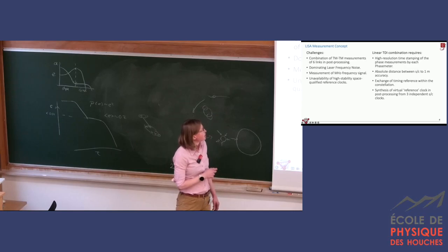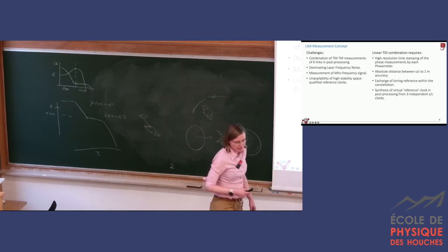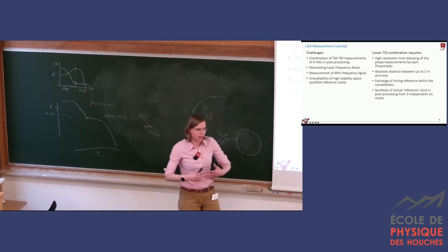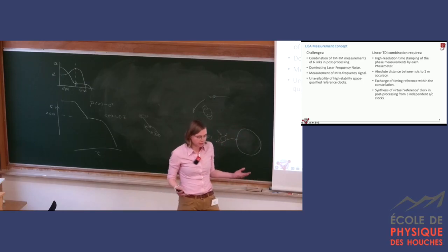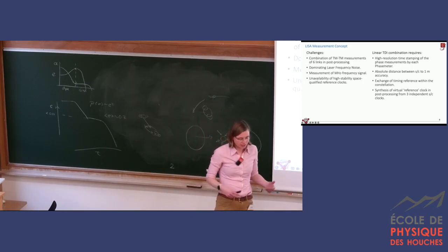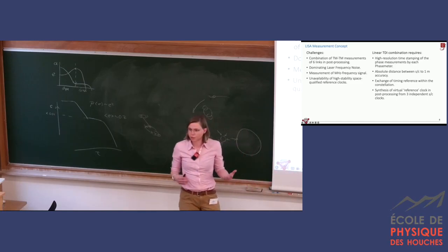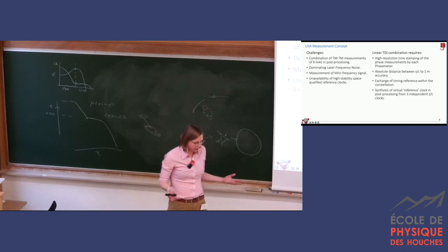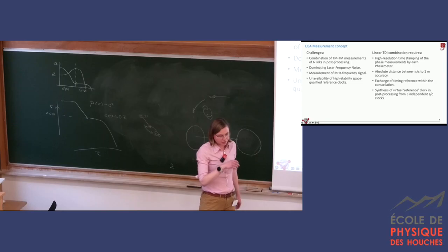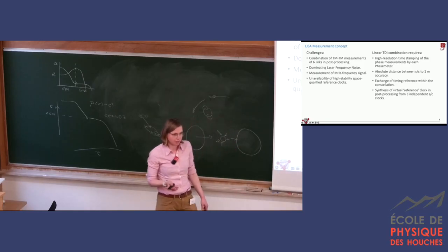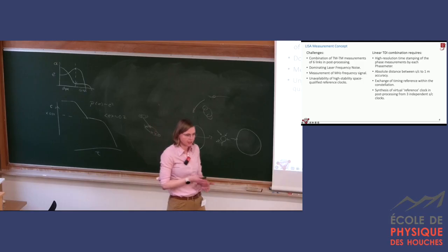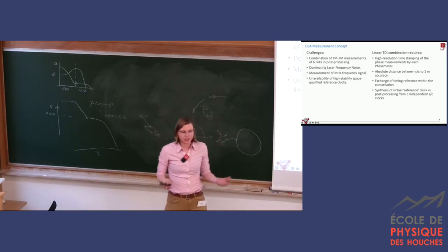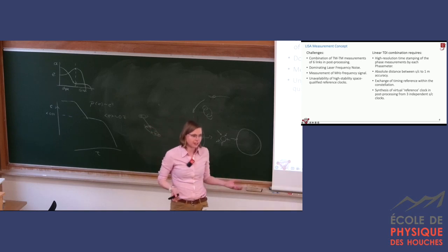So what is challenging here is, first, that we have unequal interferometers, so we have to add them up in post-processing. As I already said, we have 6 links. We have dominating laser frequency noise we have to suppress. For that, we use TDI techniques. And to support TDI techniques, we also have to provide other functions, which I'm going to talk about in a second. The big challenge is that due to the Doppler shifts, we are measuring in a megahertz regime. What is difficult for electronics is that we need much better clocks to measure these frequencies. And clocks that are precise enough and space-graded are not readily available.